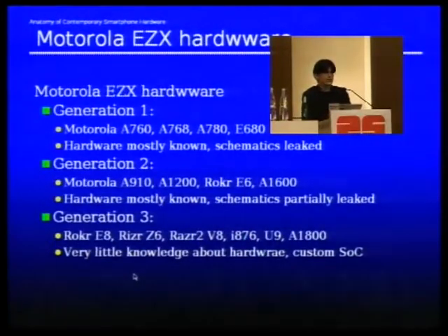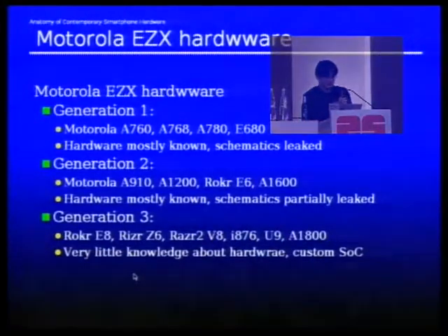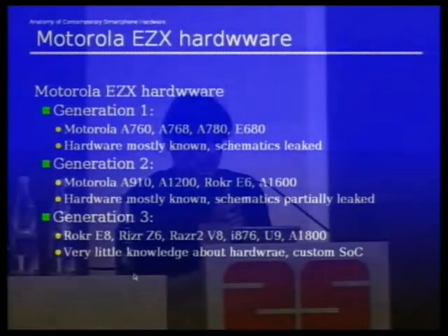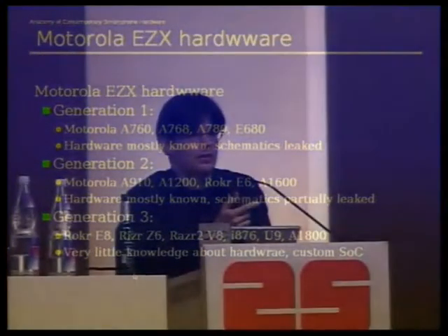And the hardware of these devices is fairly well known because the schematics have leaked quite some years ago. So people have been able to study them. In those devices, all the Motorola devices, we have a couple of key characteristics. One of them is that the audio is routed digital, so we don't have analog audio between the baseband side and the application processor side. It's a PCM interface. All of these have at least one custom ASIC, which is not a standard component that you could otherwise use. It's the power management unit in those devices.